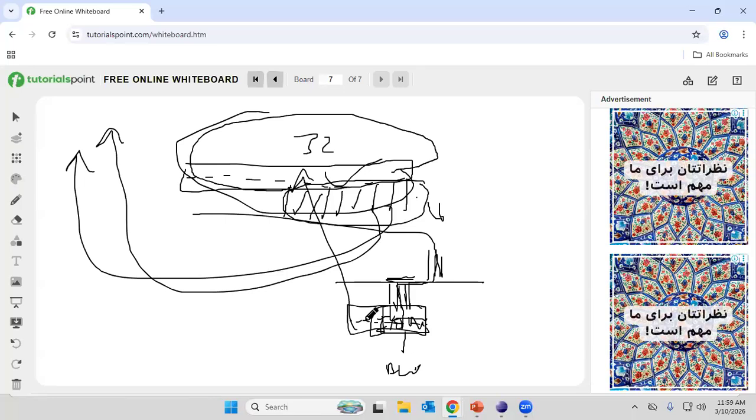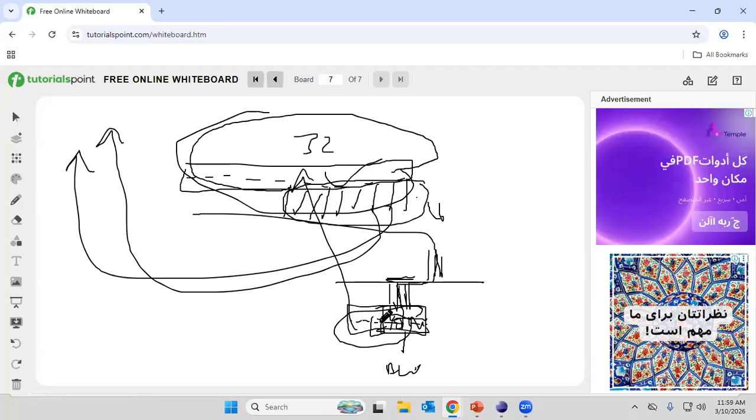And then how do I transfer these? The bus cannot move these 32 bits. These 32 bits have to move here. So if I rotate them 16 times, then this will be here and this will be here, and then I transfer them. Once we finish, if we need to go back to the original number for any reason, we do another 16 times shift and it will go back to its original situation.